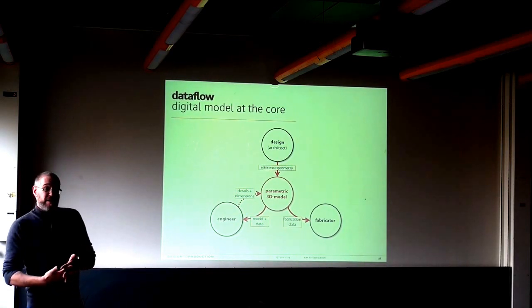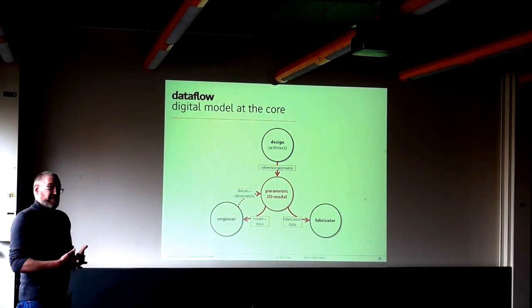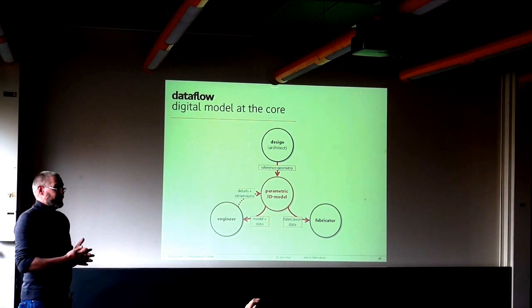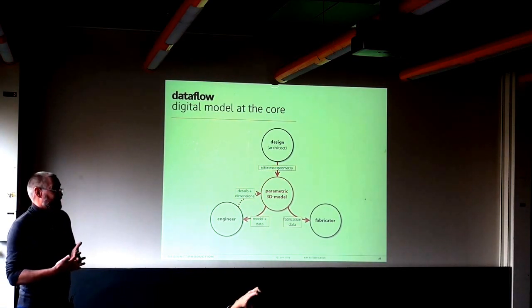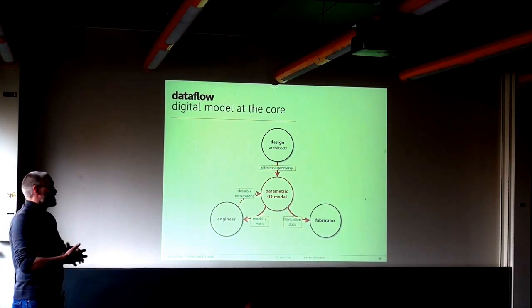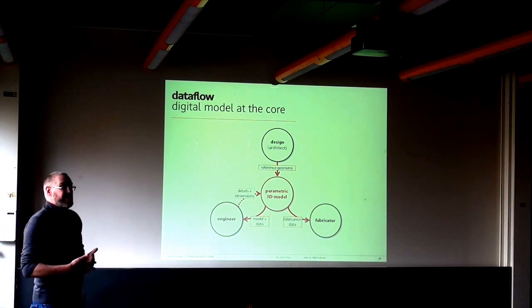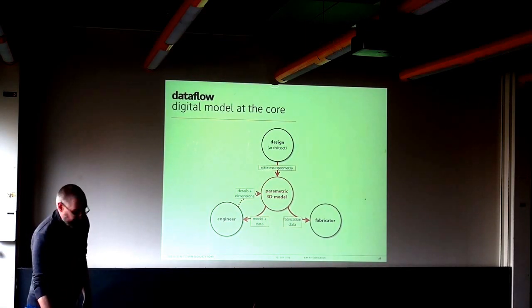That is more like a controller job on our side mostly, that says, okay, you give us your detail. Mostly they draw rectangular things where everything meets perfectly orthogonal in the node, and then you say this is the only situation that you don't have in the whole facade. Yeah, there's no right angle in there. Everything is slightly skewed, rotated, whatever. So we have to then translate this into a parametric detail and check this against the geometry of all the 2,500 nodes in there if it's really working.